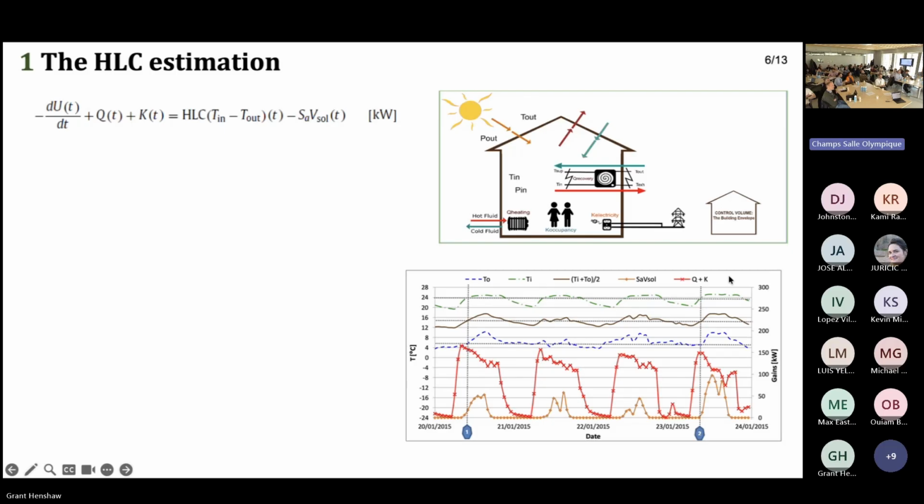So we were able to measure solar gains, heating and electric heating gains, and electrical and occupancy gains more or less, but obviously we were not able to measure the accumulation term. But if we take this point where indoor plus outdoor divided by 2 was more or less 15 degrees, and after 3 days, indoor plus outdoor divided by 2 was again more or less 15 degrees, let's say the thermal level of the building was quite similar between these 2 points.